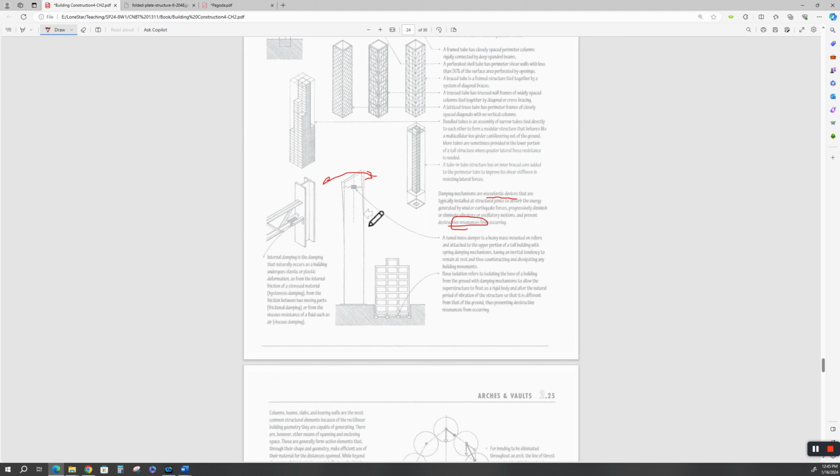It's blowing and blowing and blowing. It lets up and blows again, and it gets this thing bouncing back and forth. And that's the dynamic analysis that all structural engineers have to do for super tall buildings. And they have to do it for seismic analysis if they're in a seismic zone and they have seismic codes that they got to worry about.